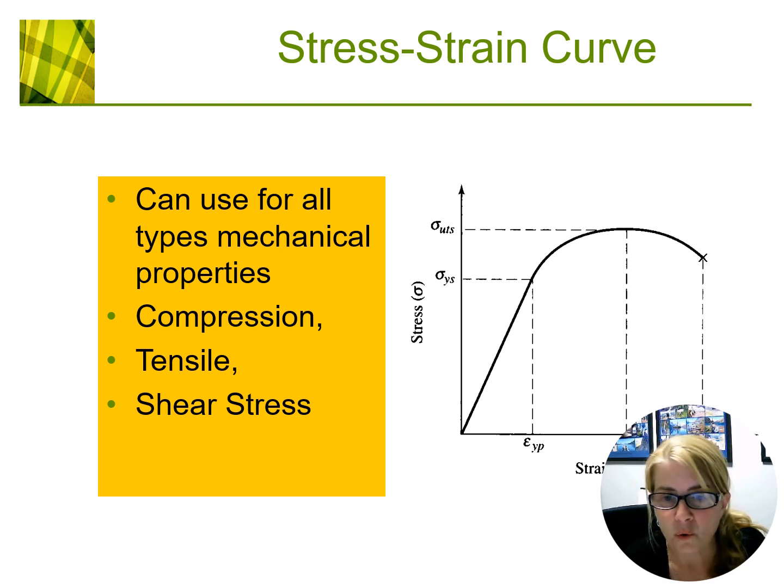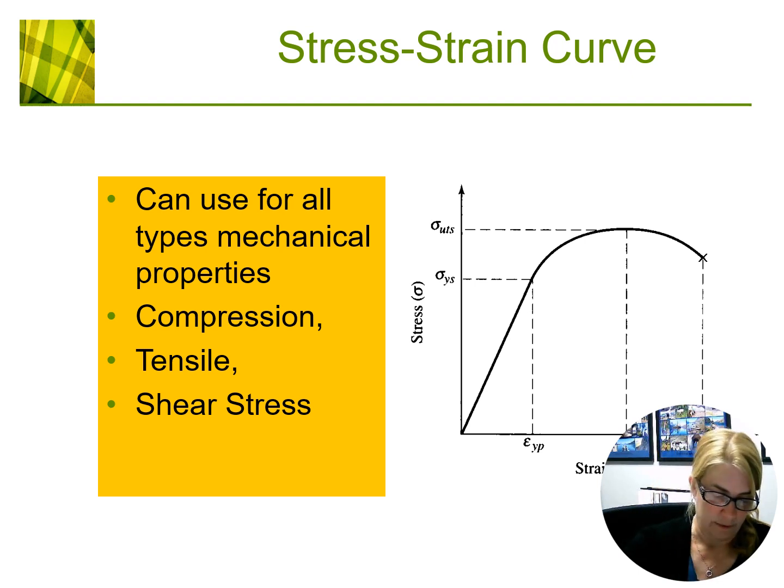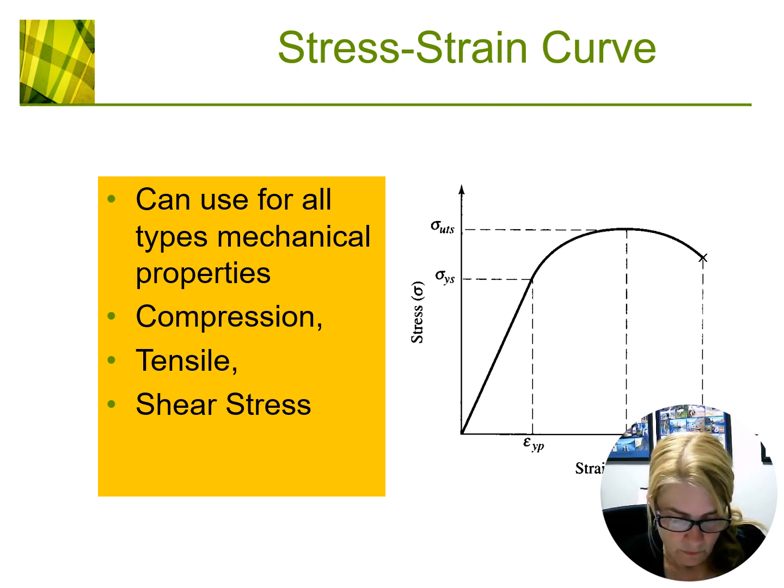Now, as you go up the stress-strain curve, starting in the bottom corner, we go up to the first dotted line. That is our proportional limit. And our proportional limit is where the stress and strain is no longer the same. It's not as stiff. The elastic band doesn't quite bounce back. There's more stress versus strain past this point, so past the first little dotted line.